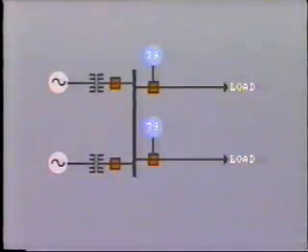I am sure that you will find on your system many transmission lines which have reclosing relays, but some of these are limited to only one instantaneous attempt at reclosing. If the breaker trips again, the relay locks out. There are even limitations to the application of the instantaneous reclosing arrangement. This is where the transmission line is located close to one or more large generators.